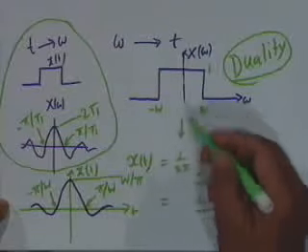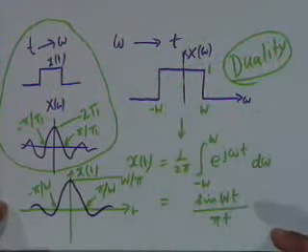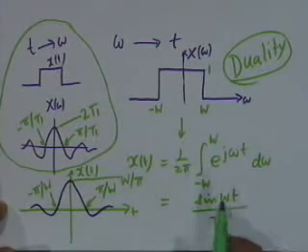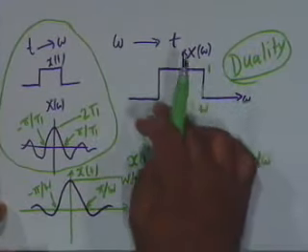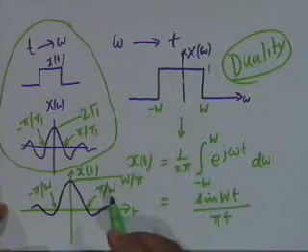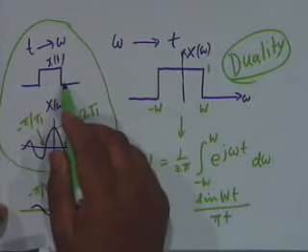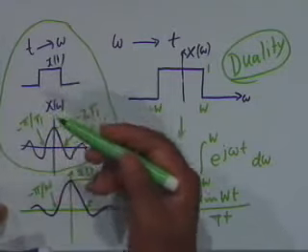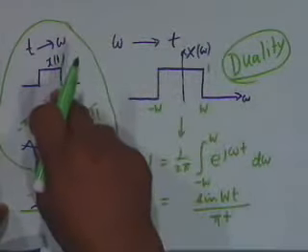we talk about such pulses, and such pulses are simple in a lecture class, but in practice, there is no signal in the world whose spectrum is band limited like this. There is no signal in the world which has a zero rise time like this. And therefore in practice, what we shall have is an approximation to this. But these idealizations help us in designing communication systems and circuits.